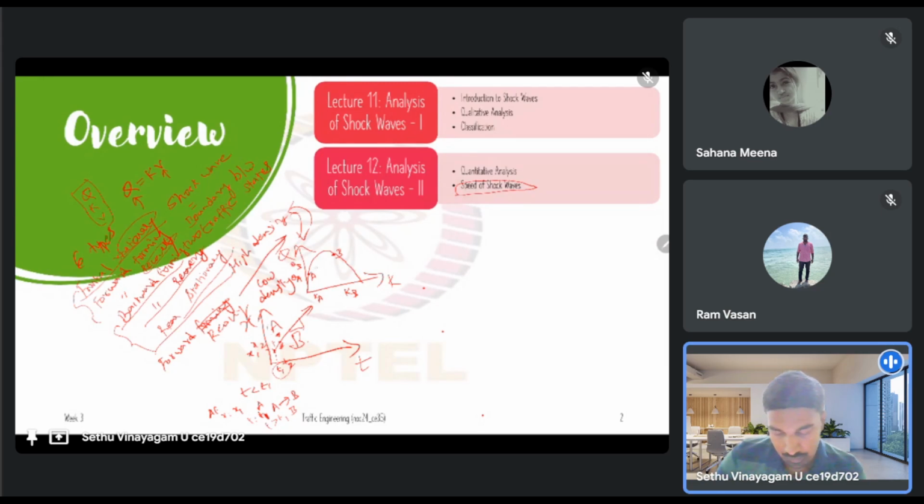So it's basically the slope of the line in the fundamental diagram that connects these two traffic states, right? If I connect A and B by a straight line and find the slope of this, let us say the slope is WAB, then the speed of this shock wave will be WAB, right?